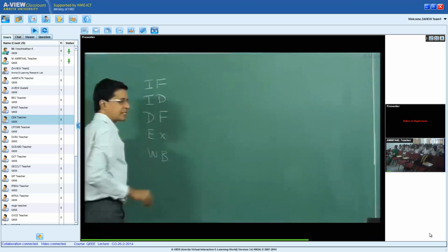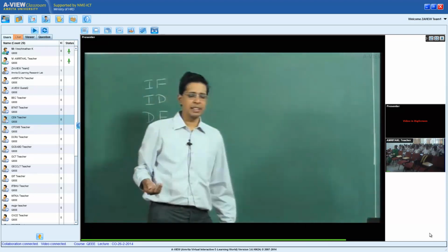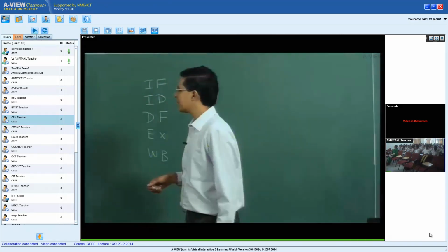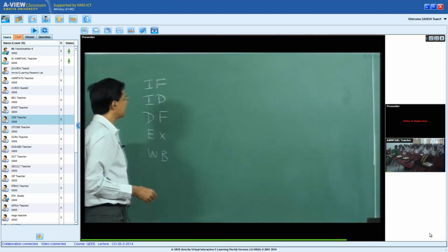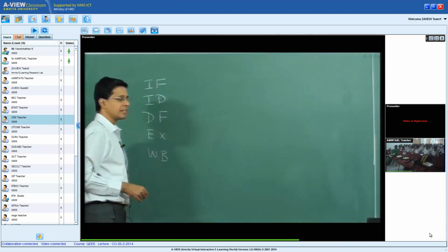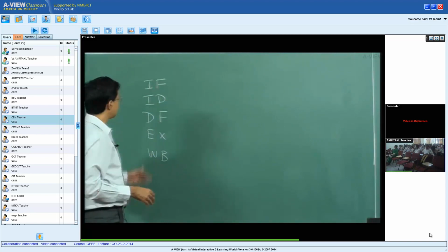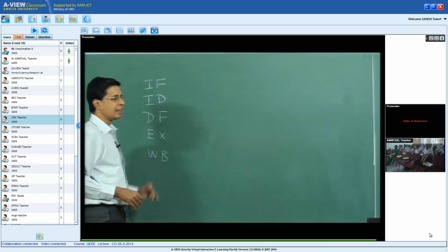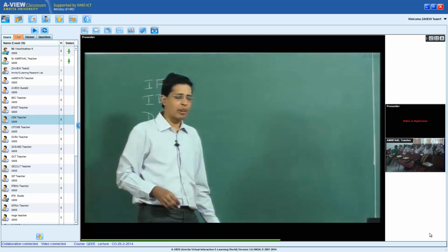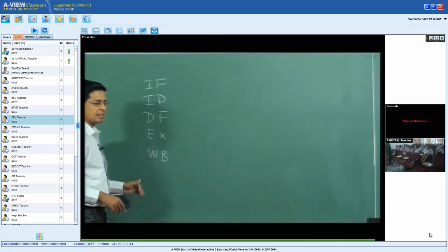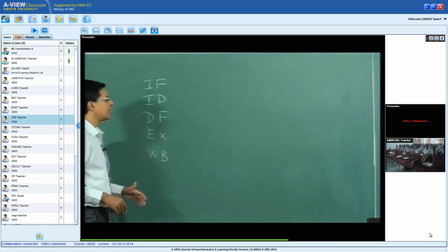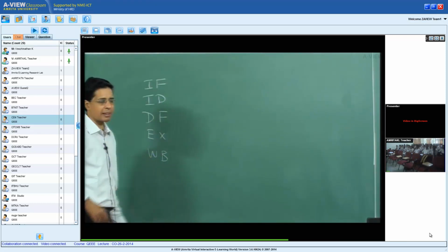In the instruction fetch stage, the instruction is fetched from the memory and then the program counter is incremented. In the decode stage, the instruction that was fetched is decoded. Then the data necessary for the instruction to execute is fetched in the DF stage. Then the instruction is executed. Then the results are stored back.